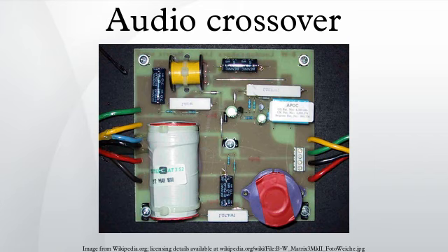Classification based on the number of filter sections. In loudspeaker specifications, one often sees a speaker classified as an N-way speaker. N is a positive whole number greater than 1, and it indicates the number of filter sections. A two-way crossover consists of a low-pass and a high-pass filter. A three-way crossover is constructed as a combination of low-pass, band-pass and high-pass filters. The BPF section is in turn a combination of HPF and LPF sections.